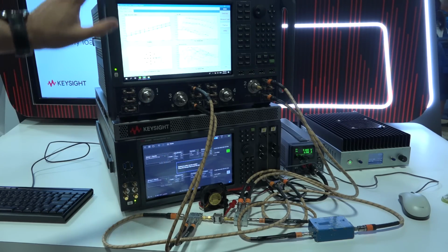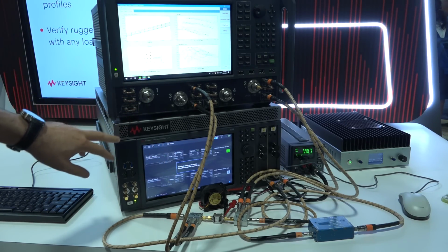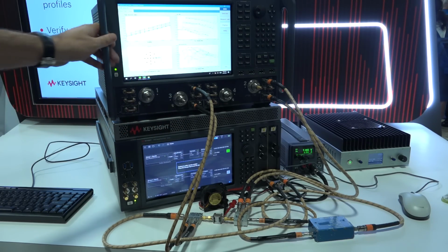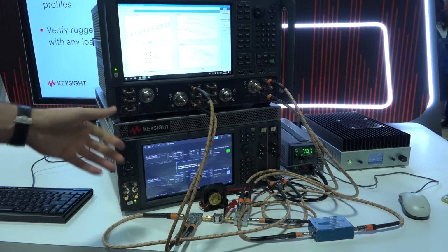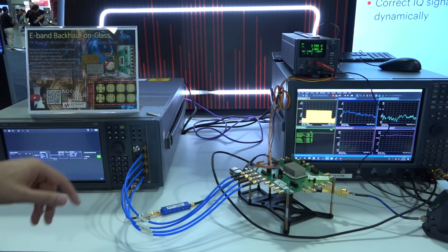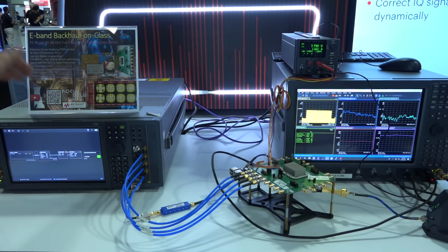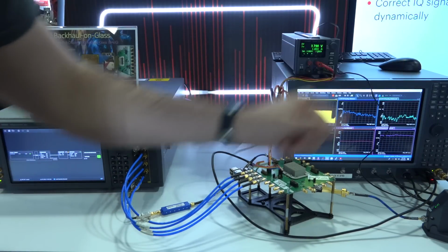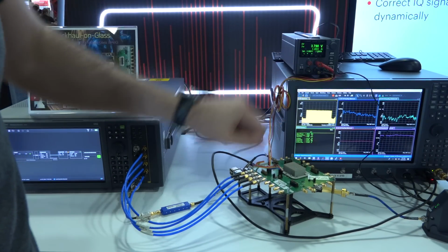at the same time. More and more we see that the combinations of the instruments from basically all the big vendors are becoming these powerhouses of strong characterization platforms. With the right software, you can pretty much do anything. And here we have active live measurements on IQ correction. We have the VXG, which is generating IQ data into an up converter, into the V3050, which is a down conversion, of course, going into the UXA.